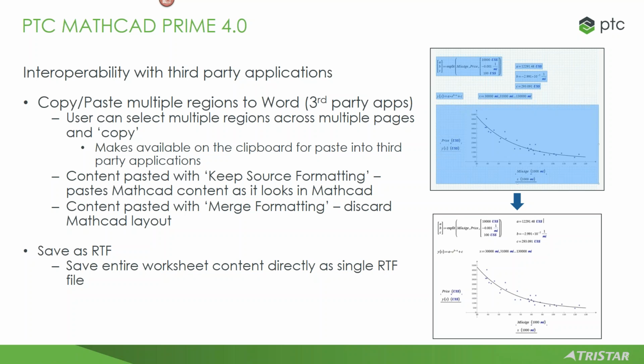If you wanted to share your math worksheets, but not everybody has a license of Mathcad, they would be able to open up that worksheet in Word. Now, what it would do is it would just take some of those symbols that update automatically inside of Mathcad, and it saves them off as images or pictures inside of this RTF file. So it's not going to update as you're making changes to the Mathcad worksheet. You would need to go in and re-export it if you made any changes, so that way they can see the latest and greatest information.